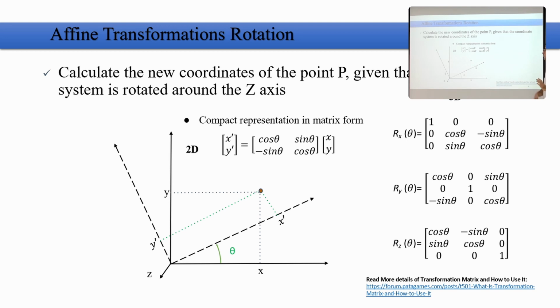So this should be very clear and simple for you guys. For example, if you're going to implement some 2D mapping and you want to rotate your robot on the coordinate system, for each one of the elements of the robot or the center of the robot, you can use these simple terms to rotate in two dimensions.